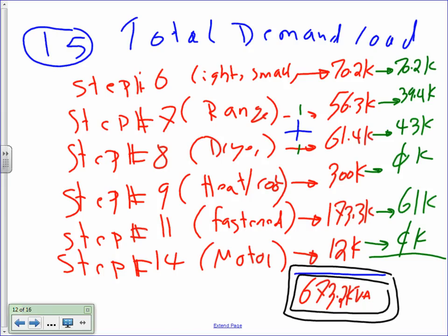I guess this could wait till after you're finished with everything, but I was just curious about the motor load for the neutral if you had 120 volt loads. Then you add them up. Okay. Then you still take 125%. Yes, absolutely. Any question, guys, about this example?